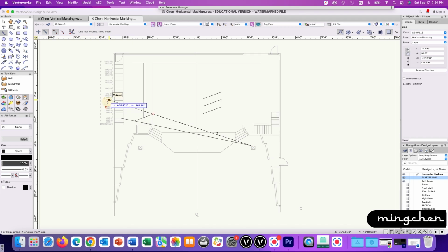Now it is time to install the second leg. Click on a new leg you created. Drag the middle point of the leg and put it in a position so that the offstage side of the leg meets or intersects the second sideline, and the middle point of the curtain meets both the second vertical reference line and one of the batten positions.